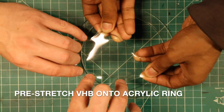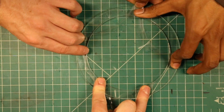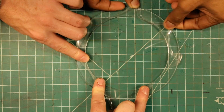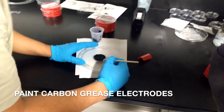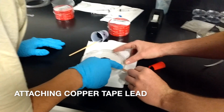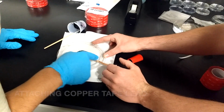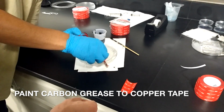Pre-stretch your VHB onto the acrylic ring by a preset amount. In this case, we're stretching by 3 times. Paint carbon grease on both sides, making sure to cover the entire electrode area. Attach copper tape to both sides to create a link between your voltage source and your actuator. Paint a line of carbon grease from your electrode to the copper tape.